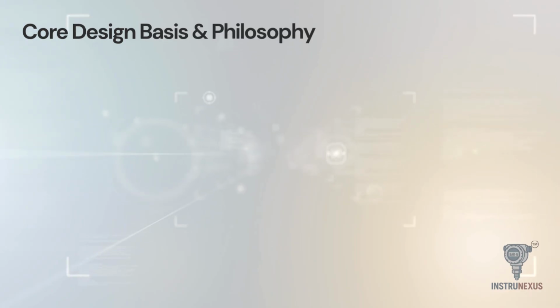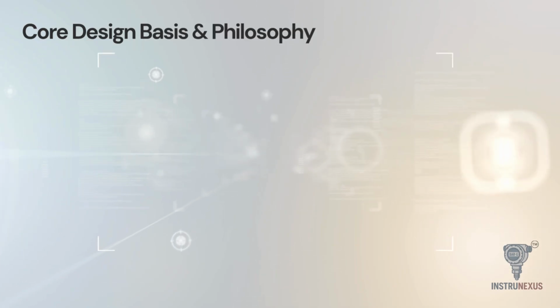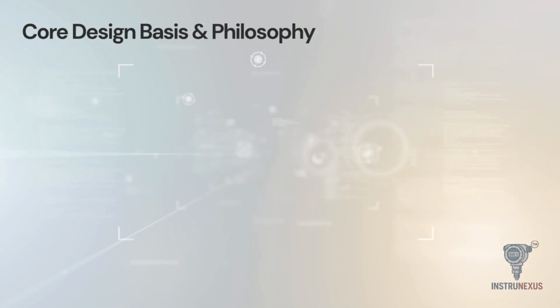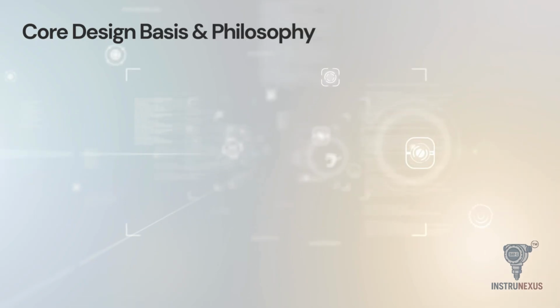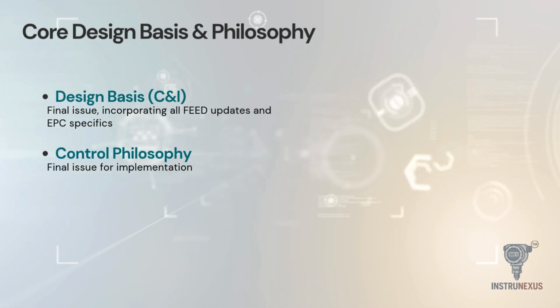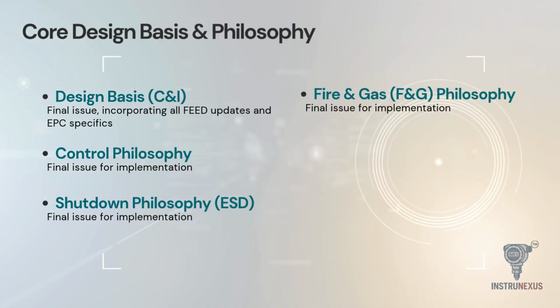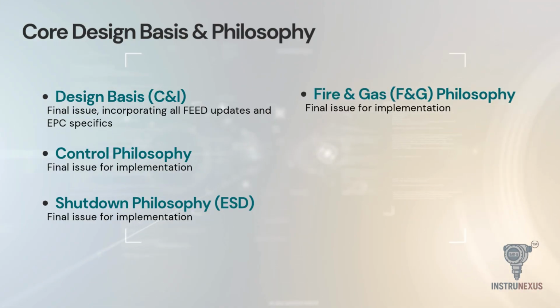We have now arrived at Phase 3, Detailed Design, often called EPC. This is the heavy lifting. First, we finalize the core design basis and philosophies. This includes the final issue of the design basis and the control philosophy for implementation. Crucially, we issue the shutdown philosophy, ESD, and the fire and gas philosophy.